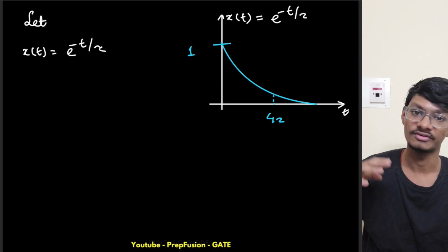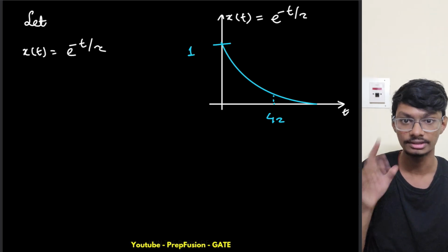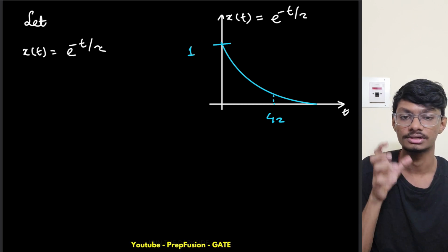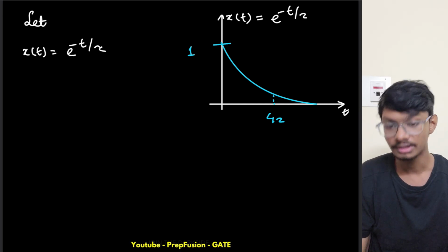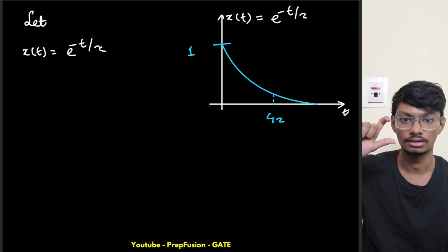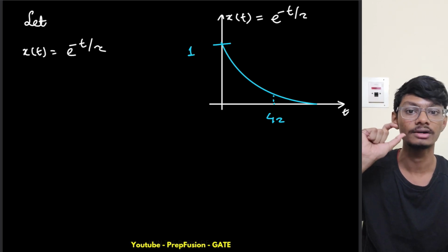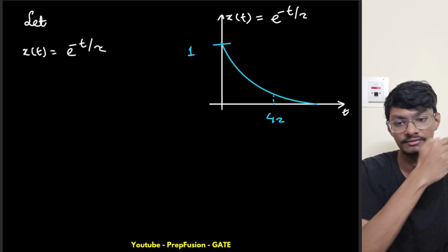Settling time has many definitions, but what we'll mainly be concerned with in this lecture is the 98% settling time, that is, the value of the signal settles to 98% of the final value. So the error band is 2% only: how much more it needs to reach the final value is 2% only. 98% means a 2% error band is left to reach the final value.